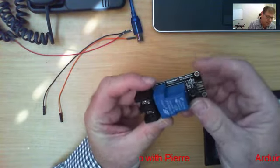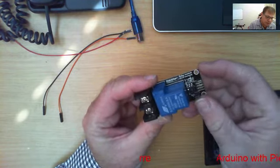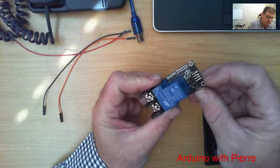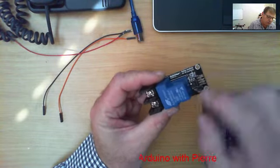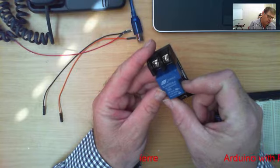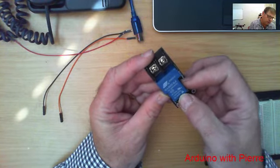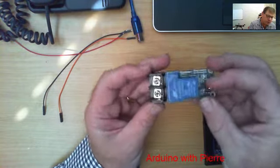This is also a relay board already configured, so it's got already the circuitry for the Arduino board on it. So again, you'll couple your VCC and your ground, and your signal will then switch this relay. But this relay has got a different current rating, and it can handle 30 amps instead of 10 amps. So 30 amp 220 volt, the specific relay will work.